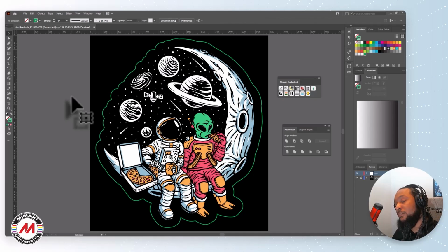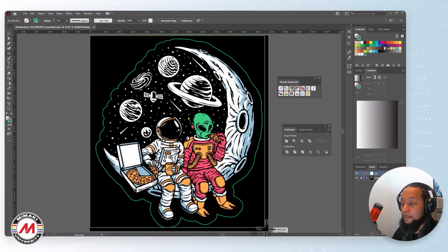But I'm going to take it one step further, and because we are Mimaki, we have the ability to do two different types of cuts. So we have what's called a kiss cut and a half cut. So a kiss cut would be, I want to cut out a sticker so that it peels and the liner is still intact on the back. But let's say I wanted all of these to be cut out individually so that I can hand out the stickers. But I still want it to be a peel kiss cut. I can make a square around the entire art file